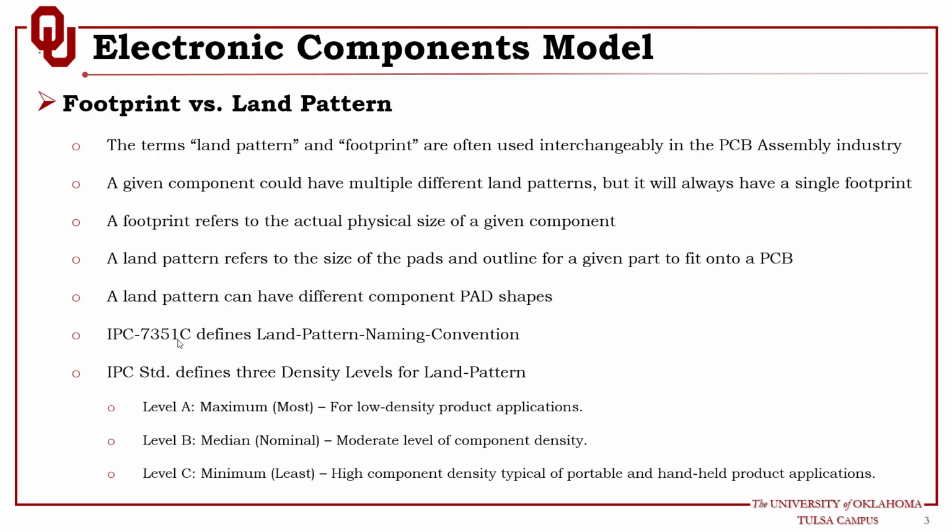Now, the IPC 7351C, which is the standard I was talking about, defines the land pattern naming convention, so how these land patterns should be named. When you go and copy a component, for instance, from the manufacturer part search panel, you will see a specific naming scheme for these footprints. And this came basically from the IPC standard.